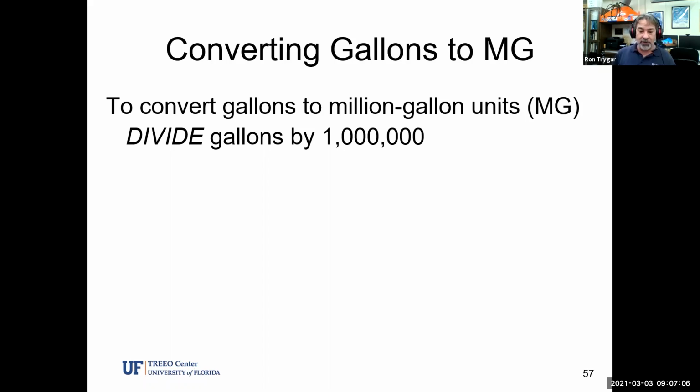The pound formula requires us to have the liquid volume in the units of million gallons, or if it's flowing water, that should be in million gallons per day rather than just say gallons per day. So the formula requires the right units.